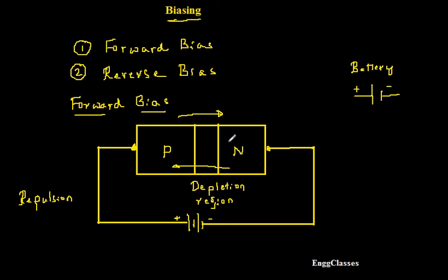Are you getting it? But we understood that there is a barrier, and it has some voltage, some potential, so that the process of diffusion stopped. If I want to make this diode conduct, the battery voltage must be greater than this barrier potential, so that only then the holes from the p type move, cross the barrier and move towards the n type material. Is that okay?